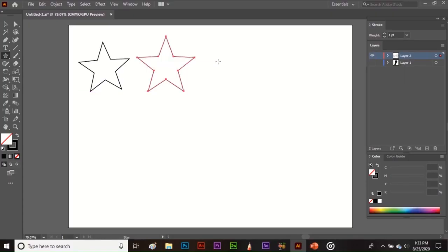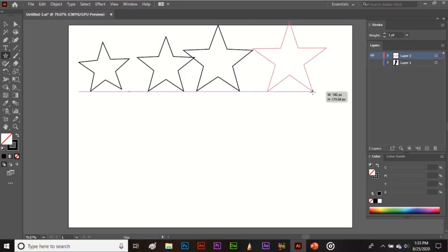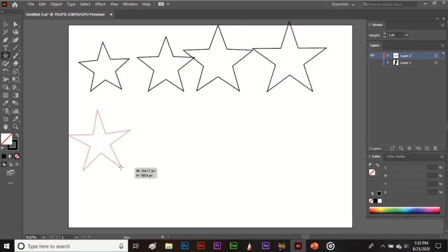Like here, I have made a 5-sided star, and here I press Shift key and its spike is constrained upright. Press Alt key while dragging to have a perfect star with smooth and straight alignment of the spikes. Press Ctrl key while dragging to control the behavior of spikes.